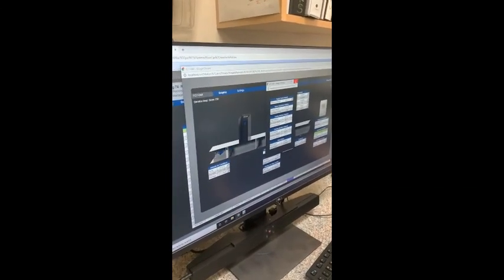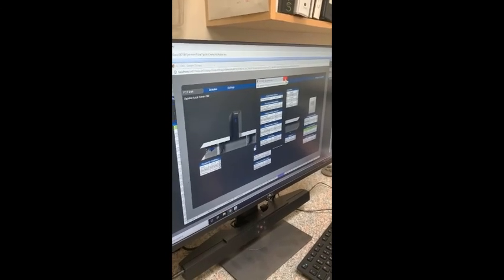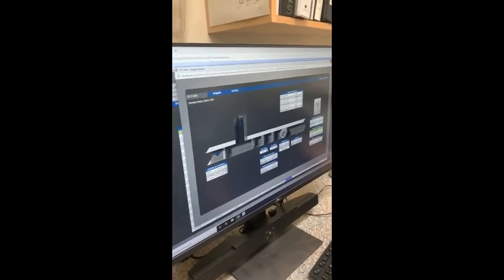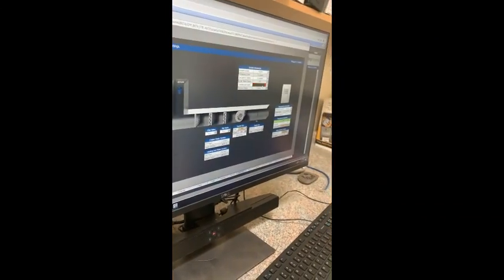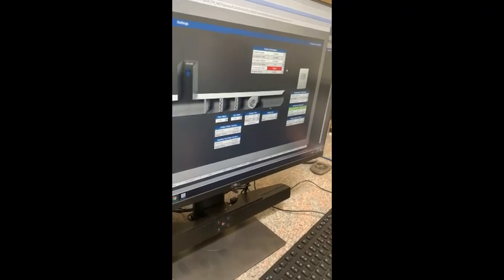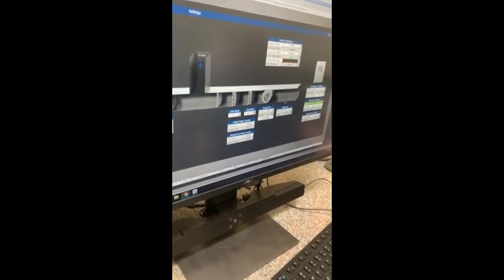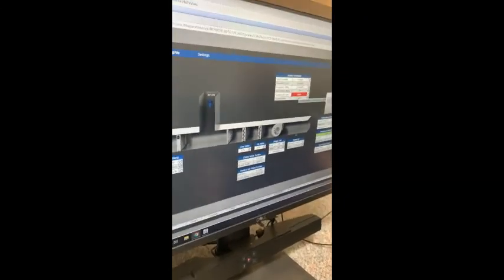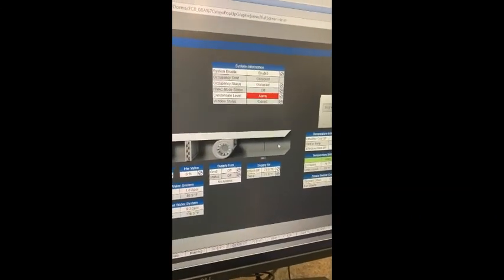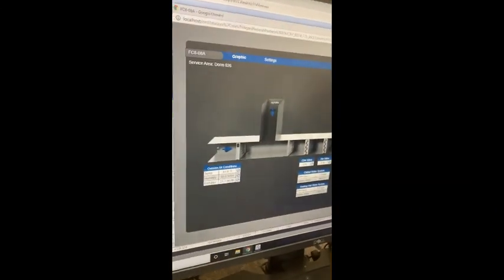You were mentioning the condensate sensor, so it'll go into alarm if that condensate sensor is tripped? Yep, there was one that was showing that. I don't remember what floor it was. We don't know if they maybe didn't wire it in properly. Those go back to those controllers that we saw in that box. It's wired back to that controller. This one here is all off because the condensate alarm is active, so it won't allow it to run.